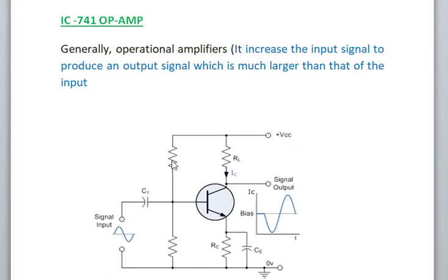This plus VCC voltage is divided by these two resistors, and the resultant voltage is a positive voltage. As it is a p-type material, it is forward biased. And the collector is reverse biased. It is an n-type material. A positive supply is given through the load resistor RL.